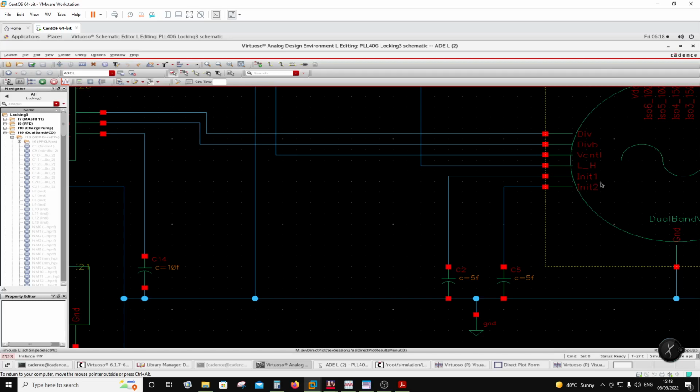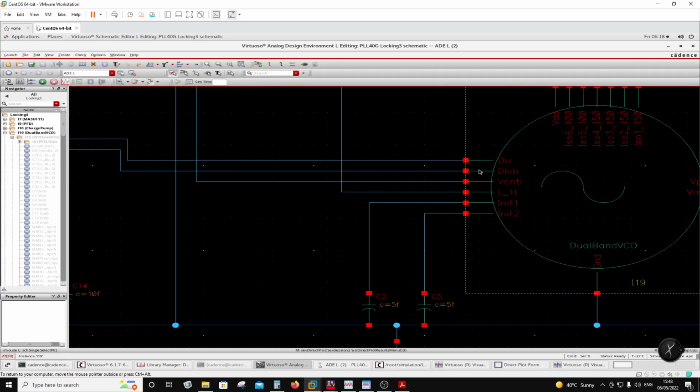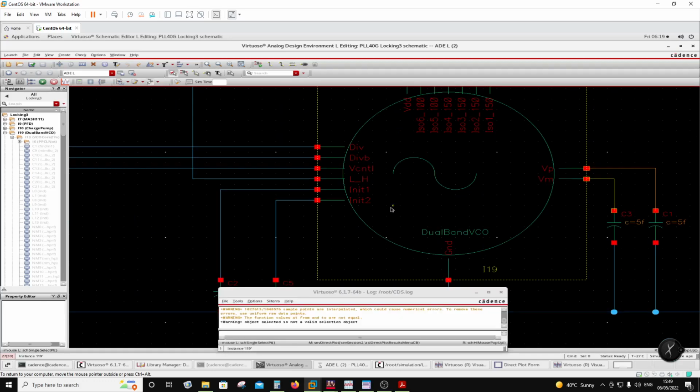So that is there. The control voltage is common for both the VCOs, and then this divide is division by 8. This is coming from the injection lock dividers, which is a 3-bit injection lock divider that divides by 8, and that basically from 2 VCOs is multiplexed using a multiplexer here. So this L/H decides which VCO output is divided and passed on to the multimodulus divider, right? So there are 2 VCOs inside this. So let's see what these VCOs are.